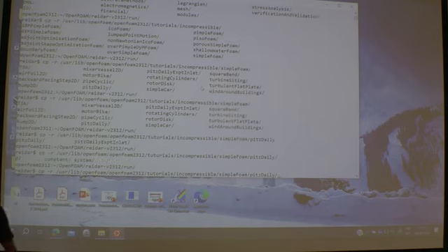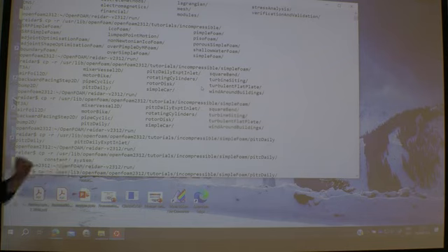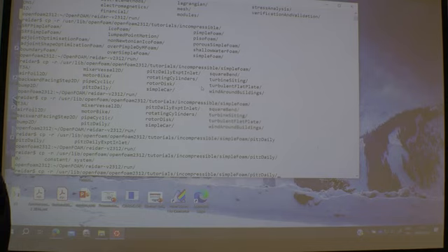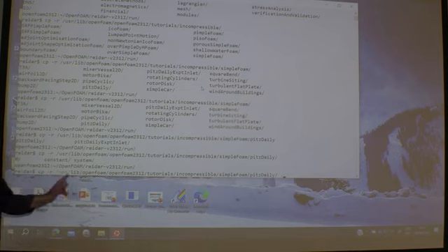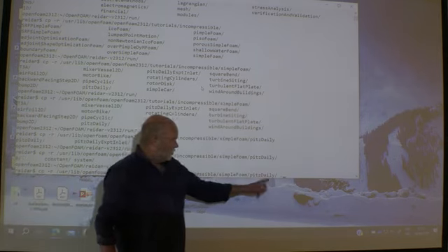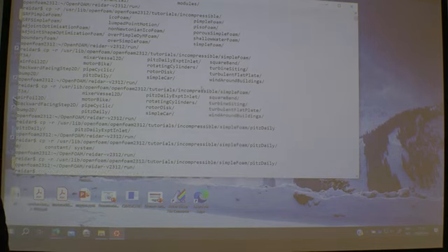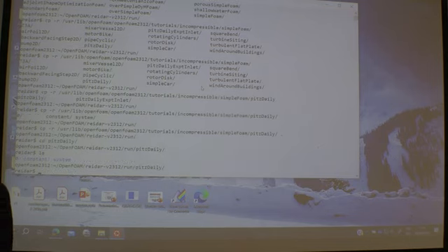No, there we have it. 0, constant, and the system folder. So that is my case. And then space and a period. So that's the command. Copy recursively from this address to where you are standing. Like that. So now I have a pitzDaily setup here. It's a standard minimum setup. You have a 0 folder, constant folder, and a system folder.